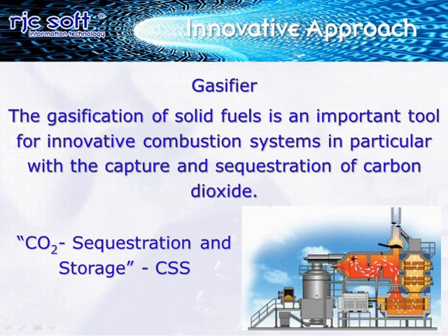Gasification is a process that converts organic or fossil fuel materials into syngas. The syngas is a mixture of carbon monoxide, hydrogen, and carbon dioxide and is itself a gaseous fuel. This is achieved by reacting the fuel materials at high temperature with a controlled amount of oxygen and steam without combustion. Gasification can be considered a source of renewable energy if the primary fuel is biomass or refuse-derived fuel.